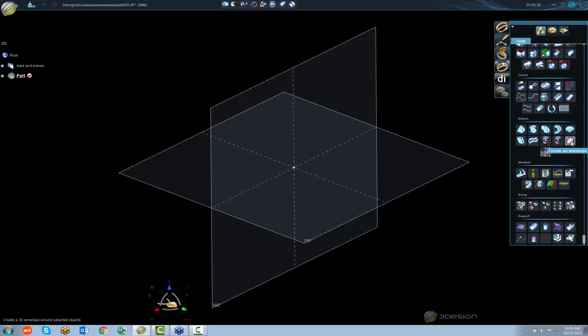These are new deforms that basically let us take an object and then deform it more freely using a mesh from 3Shaper. So we have some more integration of 3Shaper with our 3DESIGN, a lot of parametric stuff you can go back and forth. These are deform tools, so when you work on things like NURB solids, like we're used to in the regular CAD side of the program, it takes a long time to calculate. They can break your objects. NURB solids, as you know, if you've played around with regular deforms, it's going to be the same kind of caveats there. So, use simple objects if you're going to use the deforms on them.